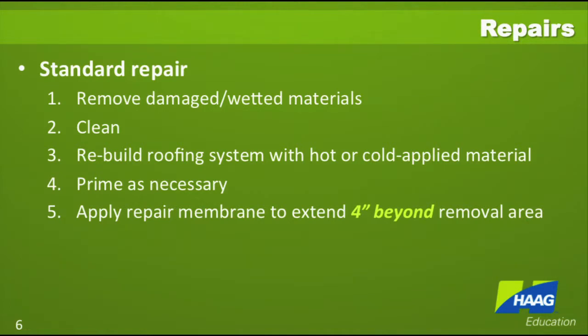Whether it's a storm-related repair or we're just talking about repairing our core, here are the standard procedures to go through. First, you'd be removing any damaged or wetted materials, including the layers of insulation if they are wet. You would be reinstalling dry insulation. Now, cleaning, this is mainly involving the spud bar and cleaning off the dirt and grime and the weathered asphalt and getting down to clean asphalt.